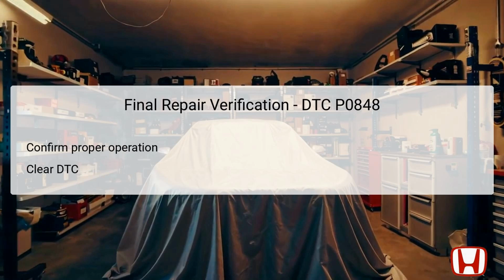After completing the repairs associated with DTC P0848, it is imperative to verify that the vehicle operates correctly. This verification includes confirming that the transmission fluid pressure switch B is functioning as intended, and that hydraulic pressure is applied properly to the third clutch. To check this, follow up with a test drive, ensuring the transmission shifts smoothly through the gears, particularly through the second to third gear transition.